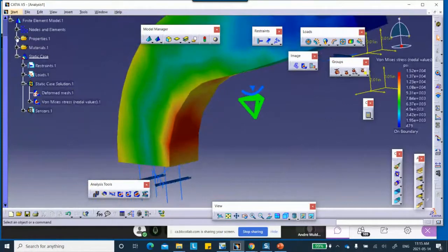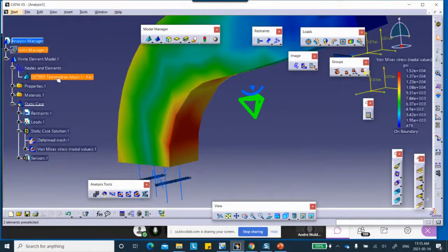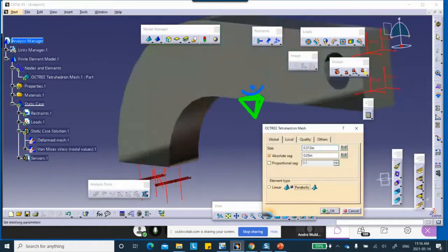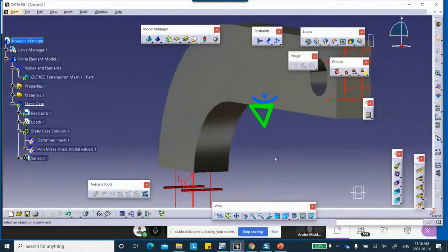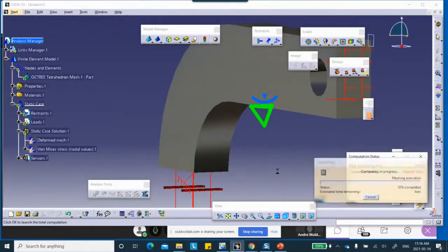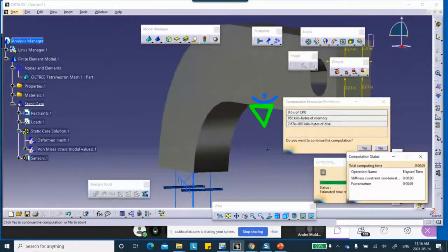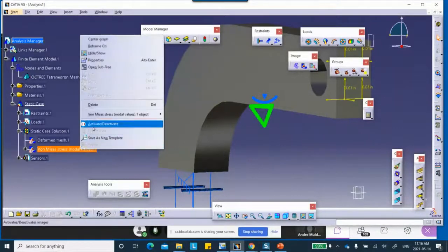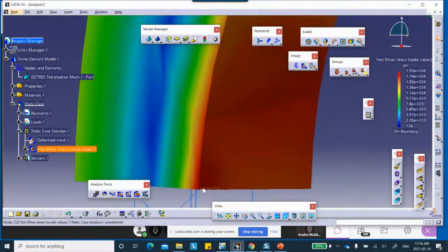Now, let's go ahead and dig in this thing a little bit further. Let me go here and make this thing parabolic. So this is linear, so let's look at it like that. So let's run it. Show you in a minute. I want to use a better mesh, so that's what I need to change. Linear to parabolic. Activate this. You see, where is the biggest stress? On this side, right on this side, but it's supposed to be pretty much exactly the same.